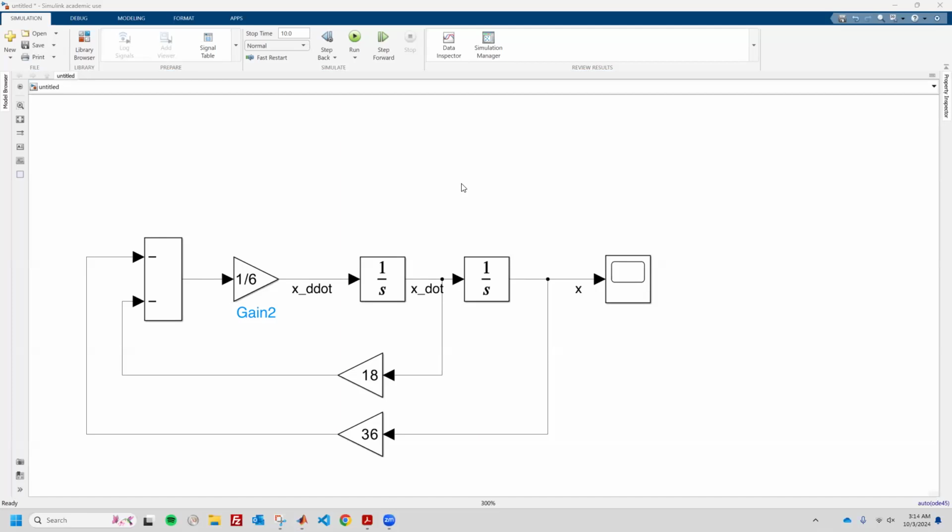So it's a good idea to have a place for external inputs coming in here at the top and having your signal coming in all the way from the left. Just good practice. So now you have this h of t signal coming in, and all you have to do is connect this here. So implementing this in Simulink would be super easy. Let's see how that works.